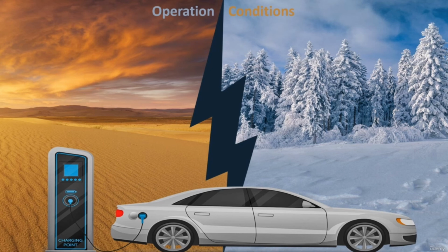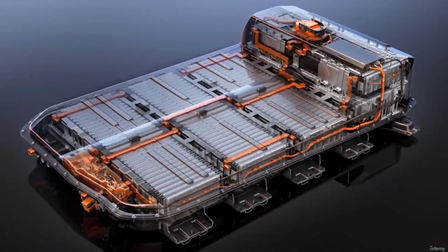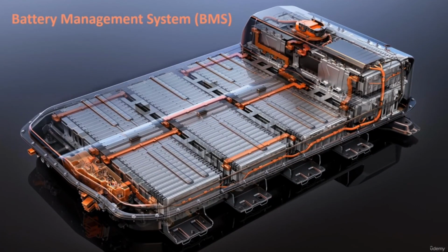This might require active cooling to guarantee a longer cycle life. Lower temperatures increase the internal resistance, which effectively lowers the power and energy density of the batteries, but only when kept at lower temperature. Batteries of electric vehicles consist of many interconnected cells in combination forming a battery pack.